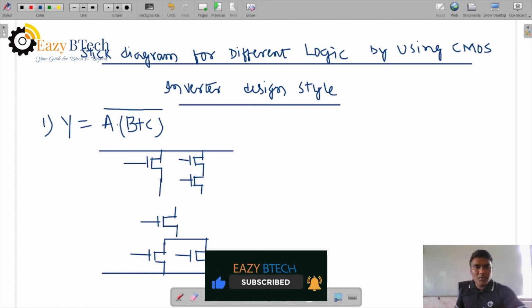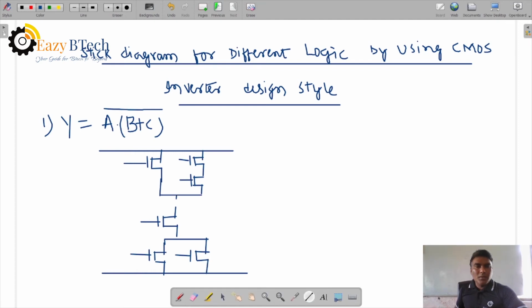Let us say this one, right? So we can join this, and from here we can take the output. This is a circuit representation of the given logic. First you can draw the enhancement mode transistor. Then you can draw the complement of NMOS. Right? So bubble across this gate, bubble across this gate, bubble across this gate. So it is A, B, C. Understood this one?